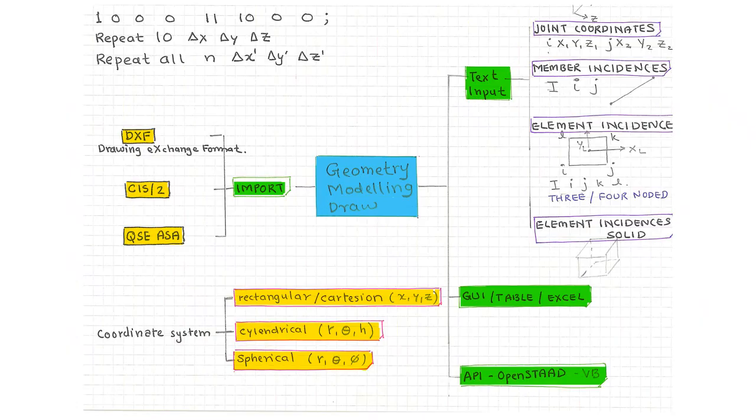So when we run STAAD, we create a geometry, and we assign property to the line or beam members. Then we give some specification, like if we want to release or offset. So they are called specification. Geometry, property. In property, we give cross section and beta angle, like how the member will be oriented. That we call beta angle specification.